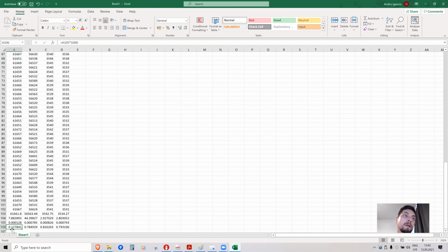But if we did 10 separate samples and we removed top and bottom values, then we can see that the noise magnitude is reduced significantly. So sampling, removing top and bottom, and then calculating the average removed noise the best.